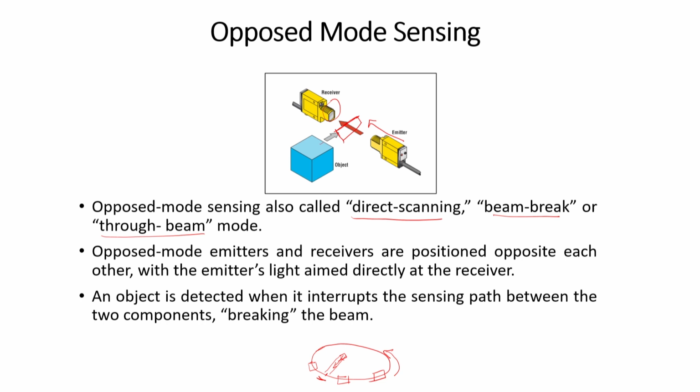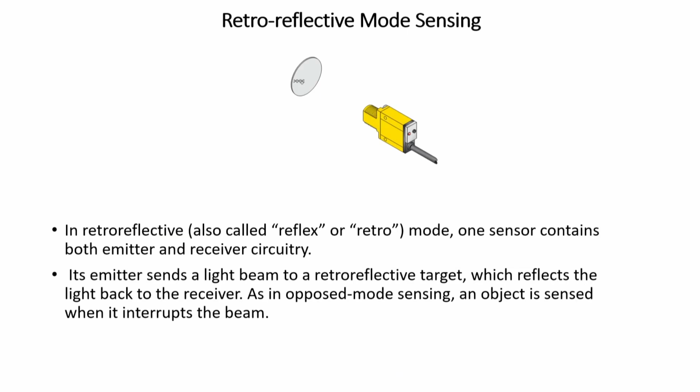So they use this kind of opposed mode sensing. Let us say you have two sensors here. As the luggage comes here, it senses that the luggage is approaching, then it immediately stops this particular belt and allows this whole thing to move fast. And in the same way, wherever the chute is, just before or just after it, you are going to have a similar opposed mode sensing technique. So this is used very much in terms of the position of a system.